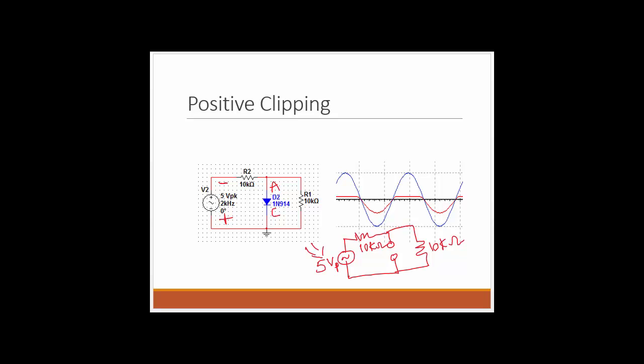So again, if you observe the input current, I'm talking about a negative half cycle. The input current coming from the source flows through this resistor, but when it enters this node, it cannot go towards the path of the diode because the circuit is open. So the whole current will flow through the actual load resistor. This circuit is similar to, so I can basically completely erase this part of an open circuit.